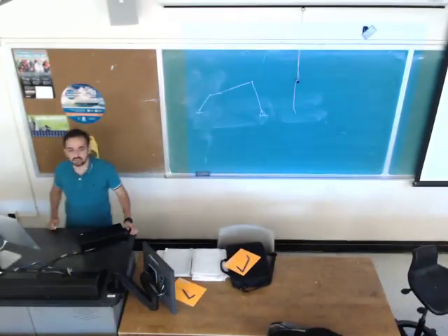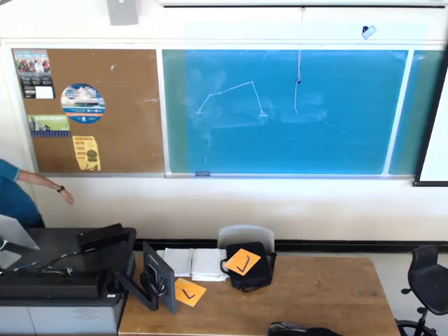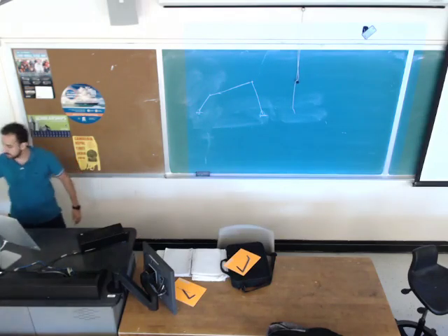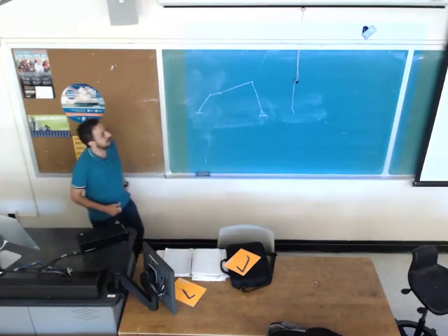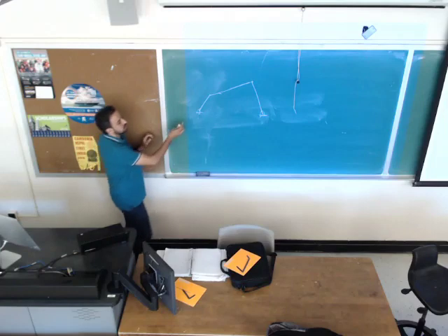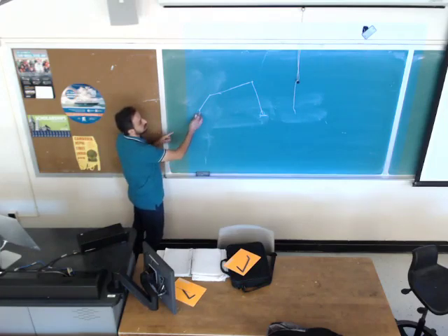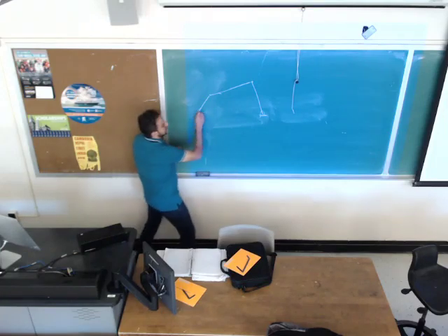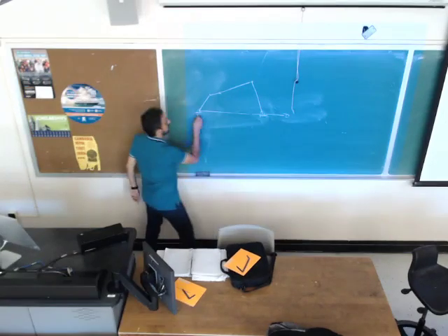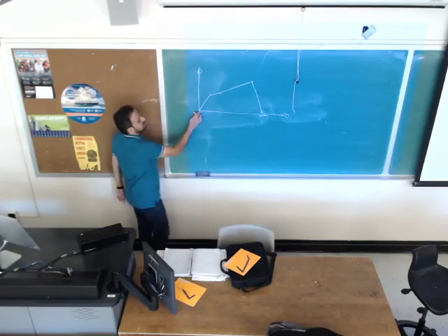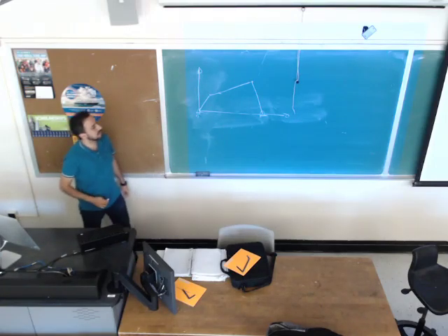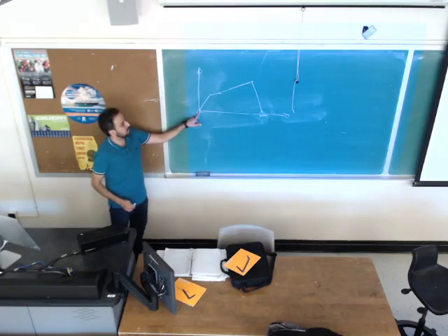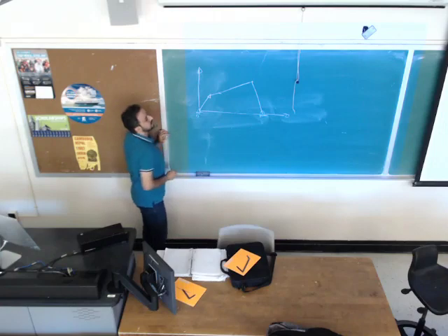The first thing that you need to do is treat the links as vectors. So I have 4 links, so I'm going to have 4 vectors. Each vector has a starting point and an ending point. Since this joint is going to be the origin of the coordinates, it's better that you pick this point as the starting point of this vector, so the ending point is going to be this.